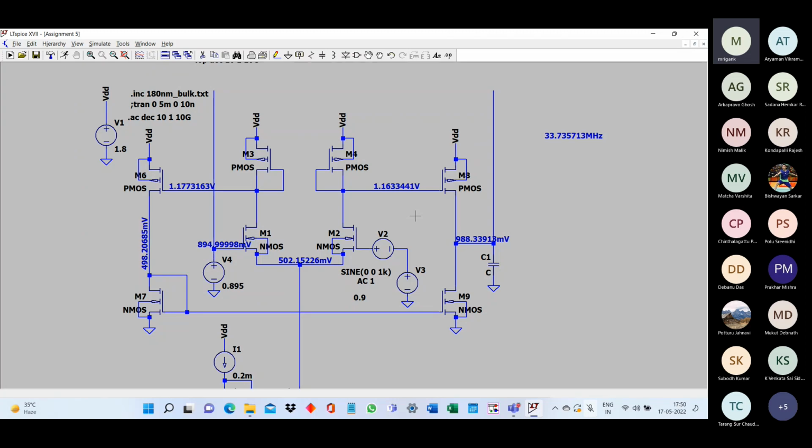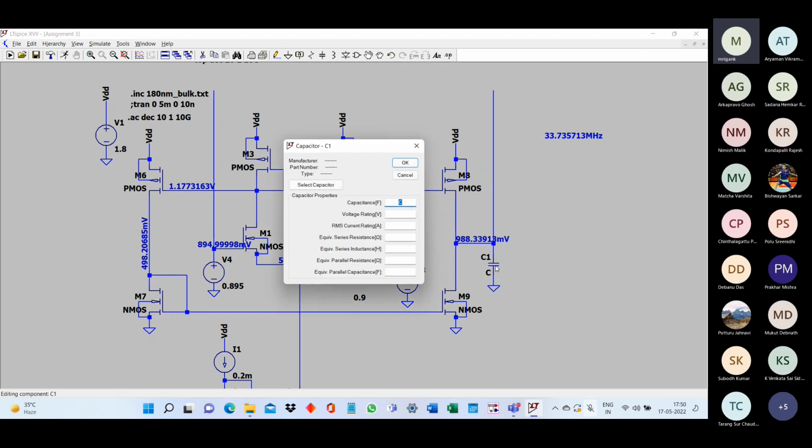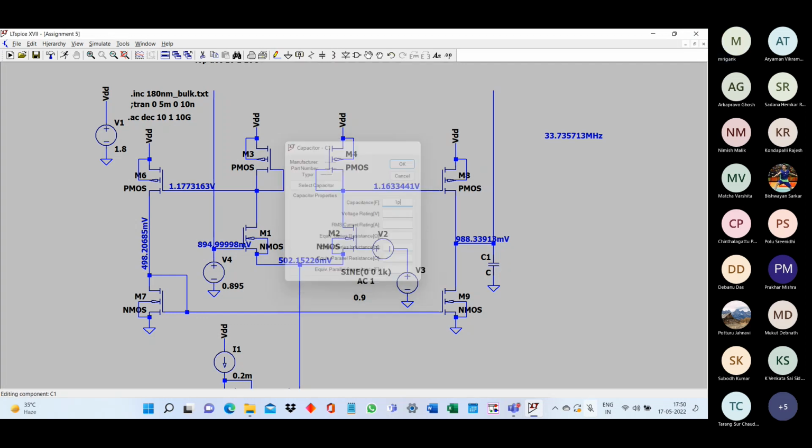We just need to push it further down. That's why we can keep a sufficiently large capacitance at the output pole directly. Miller multiplication will not work in this case because it works only when the first stage has higher impedance. In that case only, after Miller multiplication, you will get a dominant pole at the output of the first stage. Here it will not happen.